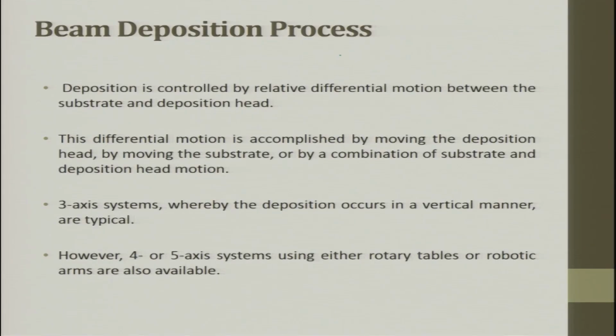If you want a flat surface, you can either move the laser, or the table can be moved. But if you move both, what you get is a taper.